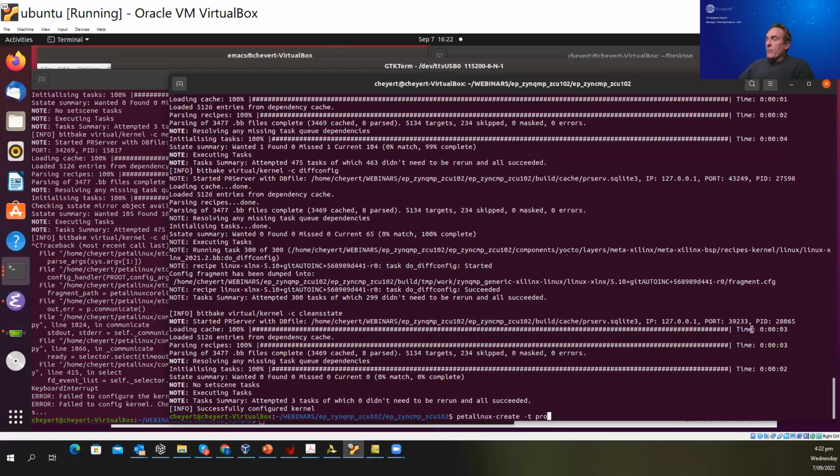The main difference on a MicroBlaze, I suppose, is that Zynq is the boot component. The MicroBlaze is not a heterogeneous device, so you will not have things such as ATF, platform management firmware, or a first stage bootloader. Those are all components that will not be built. So the bootable image format and some of the terminology will be different, although the flow is typically the same.